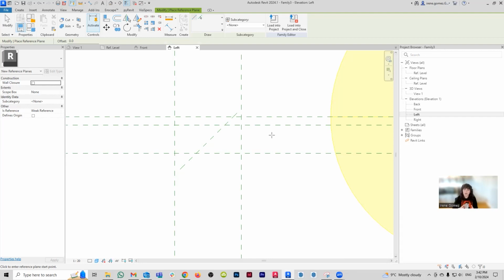So what you need to think about is, when you're setting a work plane, what is the direction that you want that geometry to be generated on? So for example, what I'm intending to do is create an extrusion that then I'm going to use voids to cut into the final shape that I want. It's not a perfect method, but it's going to be good enough. Now, the problem with that method is that this reference plane is going in the wrong direction. I need to actually go in the opposite. So just keep that in mind.